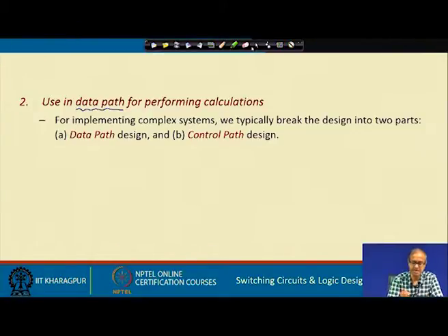The basic idea is, while you are designing a relatively complex system, normally for small systems what you do, as you have seen, if it is a sequential circuit, you break it up into some kind of specification in terms of a state table or a state transition diagram. Then following some systematic steps, you arrive at the final design. But let us take an example.